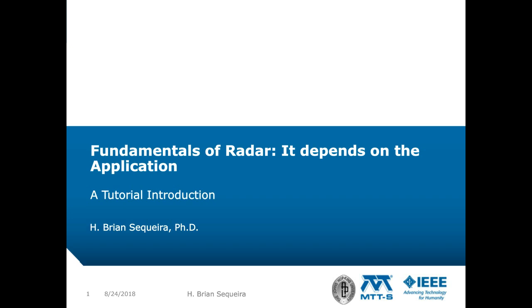Irrespective of type, a radar must do work, that is, expend energy to fulfill its primary functions of detection and ranging. First, the radar must illuminate the target or scene with electromagnetic energy and capture echoes that are returned from the scene and our target. A significant amount of work done by the radar is manifested as energy expended in computation for detection and characterization of targets.